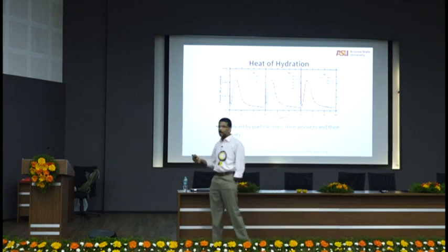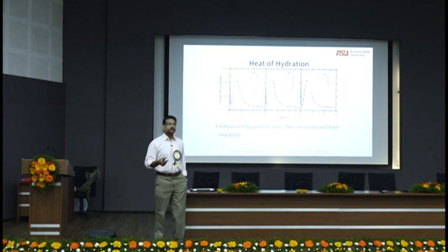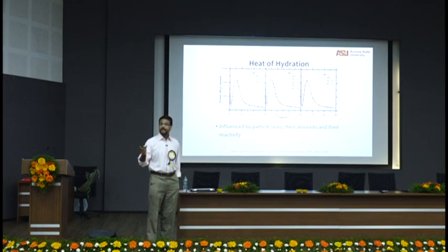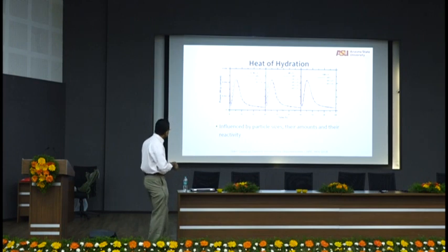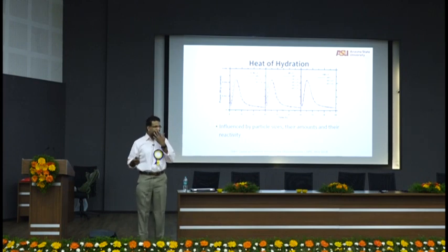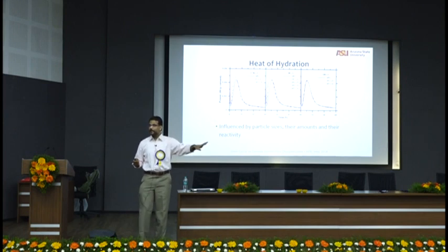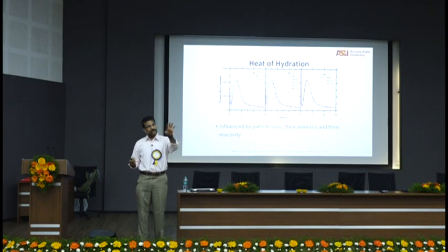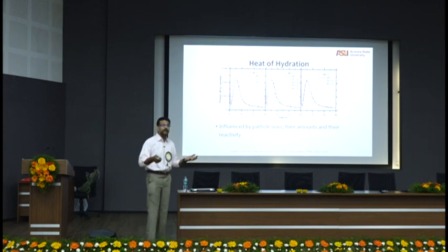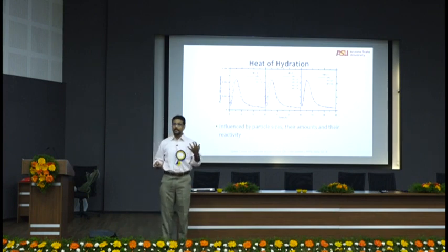And this is what is called performance by design. Not randomly putting the material, but understanding what the system does, and therefore now I can tune my system and say, don't worry, I can still do 350 kilograms per meter cube of cement, I can still get you the concrete, all I need to do is add 5% of limestone, 10% of limestone, or 5% of any filler. That is a technology that you want to come in.